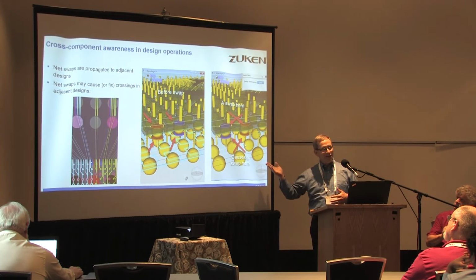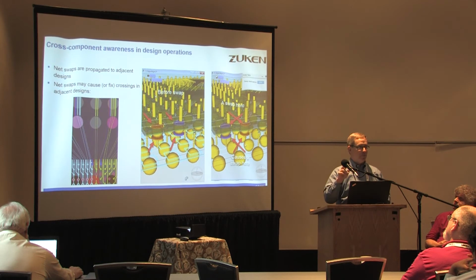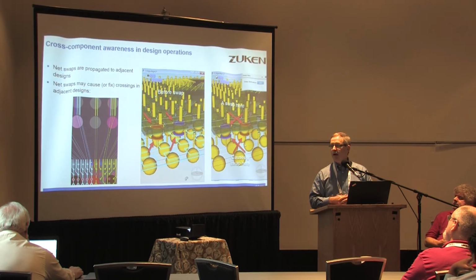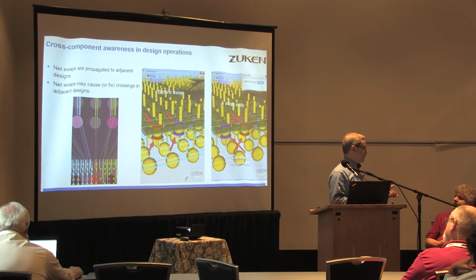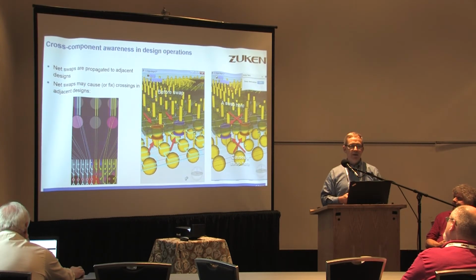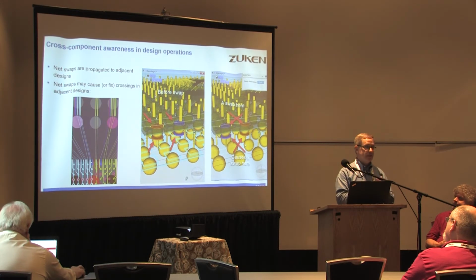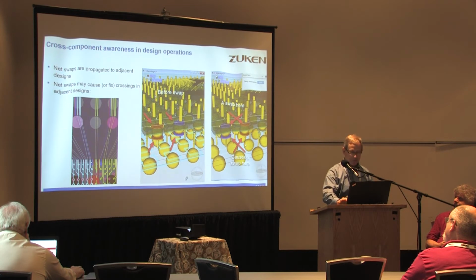And again, it's really nice to have a co-design environment where you can see the chip and the board simultaneously, and see the chip into not just the bumps, but the RDL routes and the I/O pad ring as well. So you can optimize from a connector on a board to a BGA or a pinout for a fan-out wafer level design into an IC and have a very smooth routing path to improve your routing capabilities, lower your layer count, and give you better SI performance.